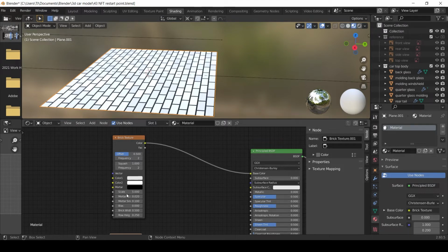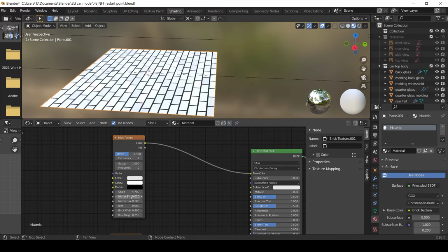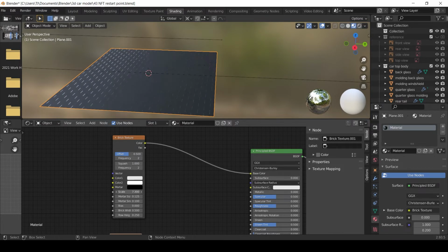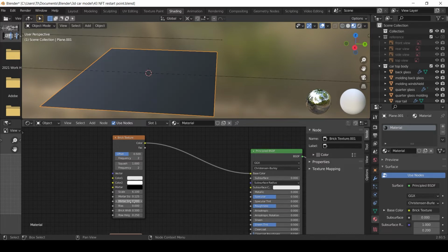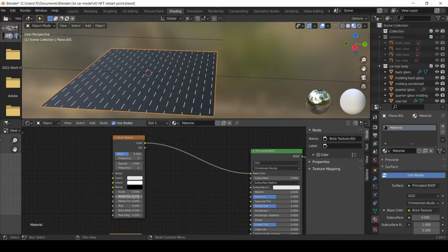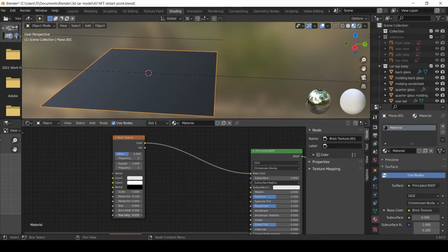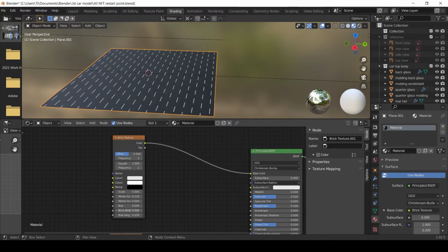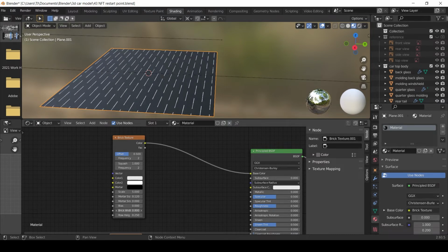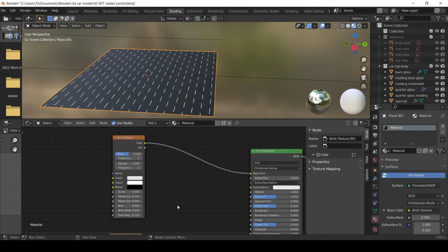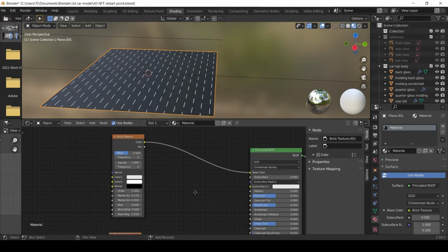And you can mess around with the scale a bit. I find that about mortar size around 0.125 works, and you can adjust the scale from there. And make sure the mortar smoothness is 0. So about mortar size 0.120 is fine as well. And here you can adjust the brick width and the brick height to your liking. So for now, that's kind of good. We can move on, as we'll come back to this later.